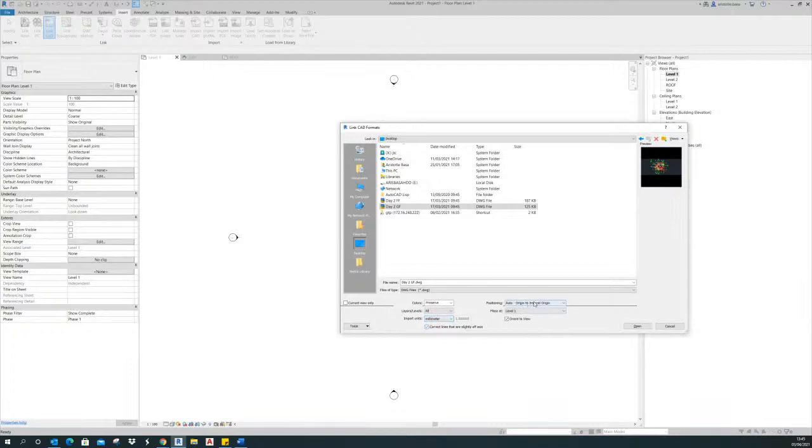And the positioning, it can go to internal origin, or you can have it center to center or manual origin. But let's just try to use manual by origin. Then it will go to the level where it is meant to go. So that's at level 1, not at level 2. You can go to level 2, 3, 4, or whatever.